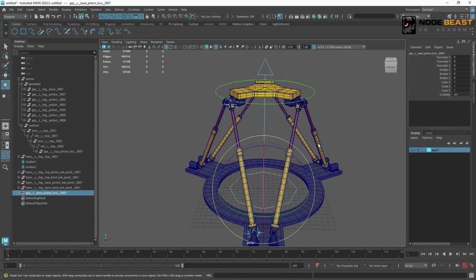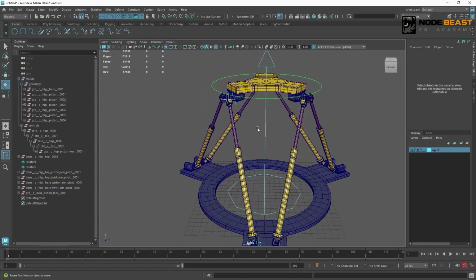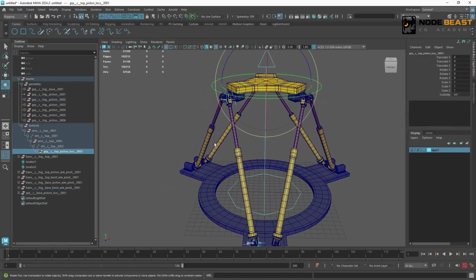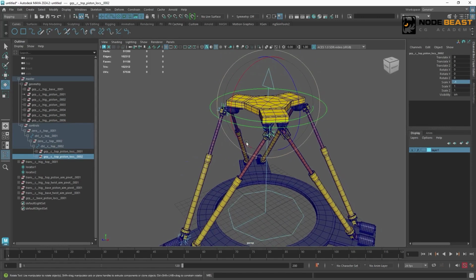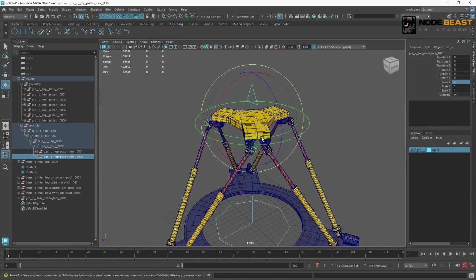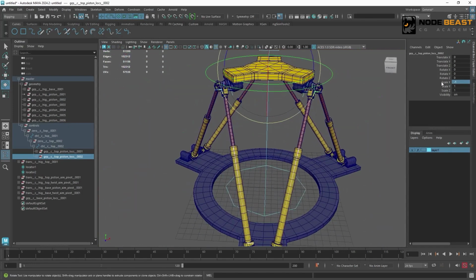Next, let's look at the next part, index 0002. We can see between 1 and 2, they are a mirror relationship. If I duplicate 0001 and change its x-axis scale to -1, then we'll see it's already at the position we want. But there's a problem here. I really don't want to have any negative values in my upper group scale. Why? It's because many features in Maya rigging don't actually support negative scale values. When we set the scale to a negative value, it can cause some unexpected problems. So here, if we don't have a special reason, we should avoid changing our scale as much as possible.